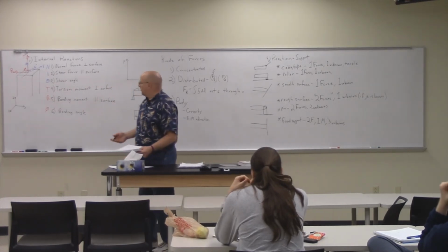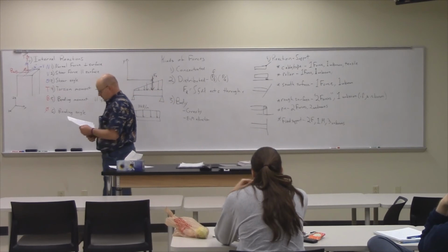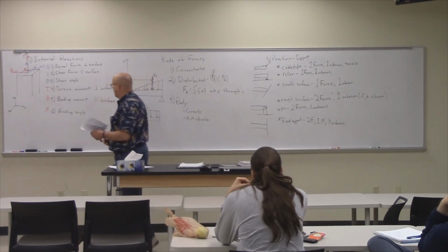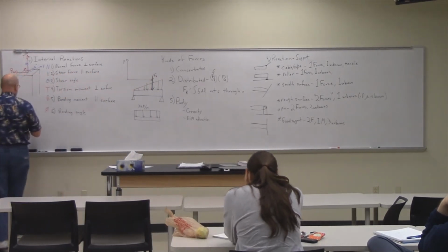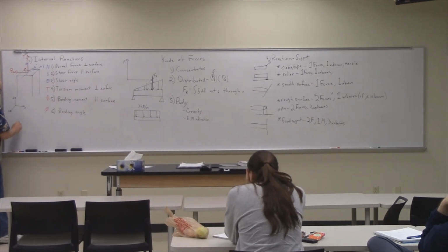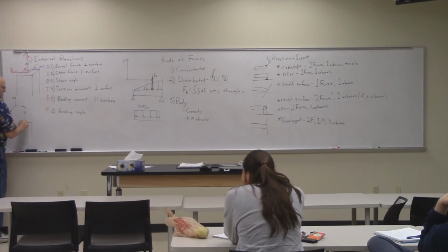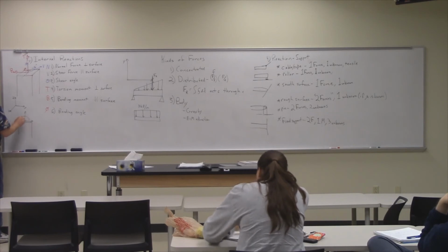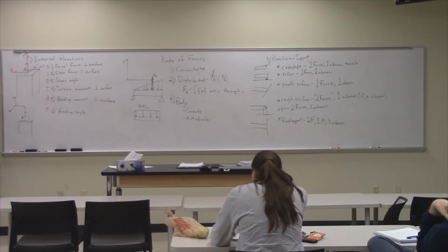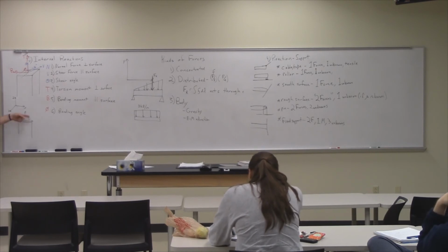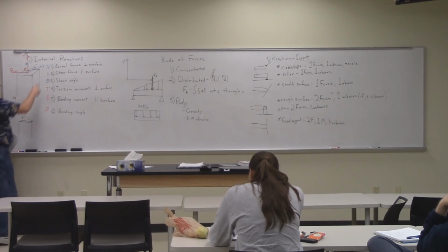And then if we have a two-dimensional system instead of a three-dimensional system, now we're just going to look at it two-dimensionally, so we don't allow for a third dimension into the board. Now I can still have a normal force, I can still have a shear force, and I can still have a moment, but the only moment that's left is the z, right? We have the x and y forces, and the moment about z. So in this case, the x and y are n and v.